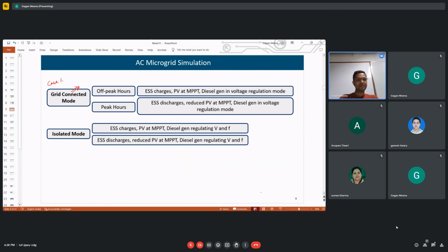It's a multi-input, multi-output system. There are two inputs and two outputs, and both the outputs are dependent on both the inputs. So here I21 is dependent upon both the pole voltages of both the inverters, VO1 and VO2. Similarly, I22 also depends upon both.